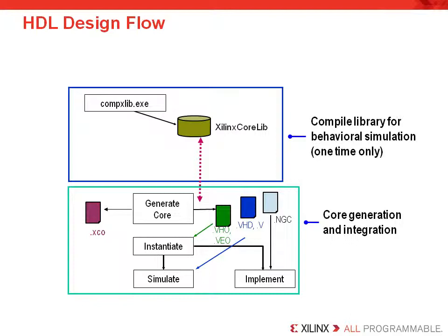Again, we will assume you have selected an HDL flow. The .vhd and .v files are the behavioral simulation wrapper files that you will require for testing your component with either ModelSim or Xilinx's own ISim simulator. These files are also made automatically.